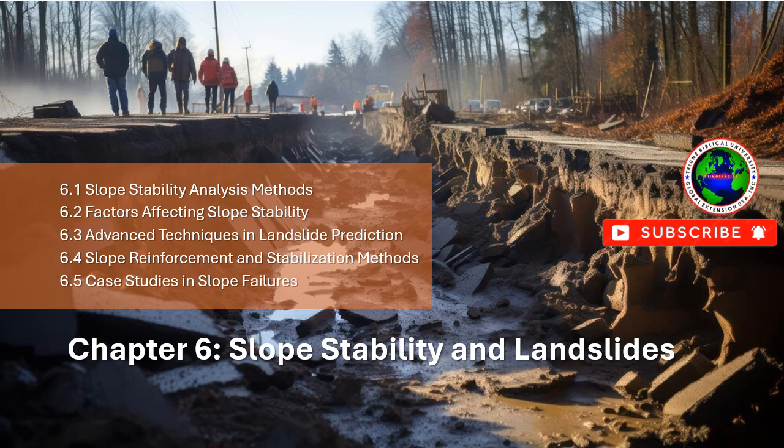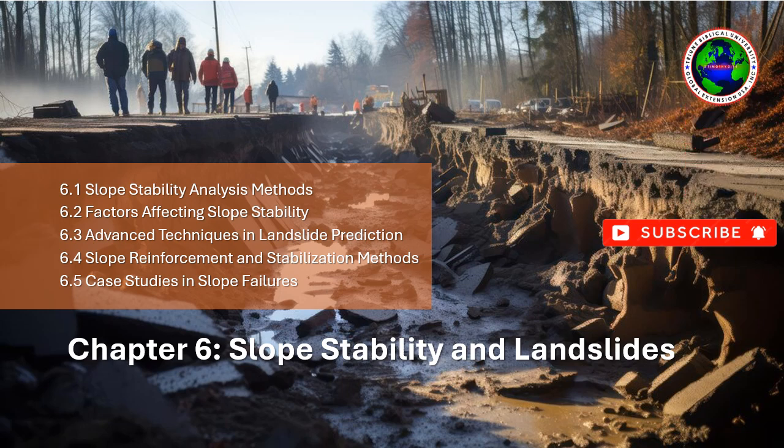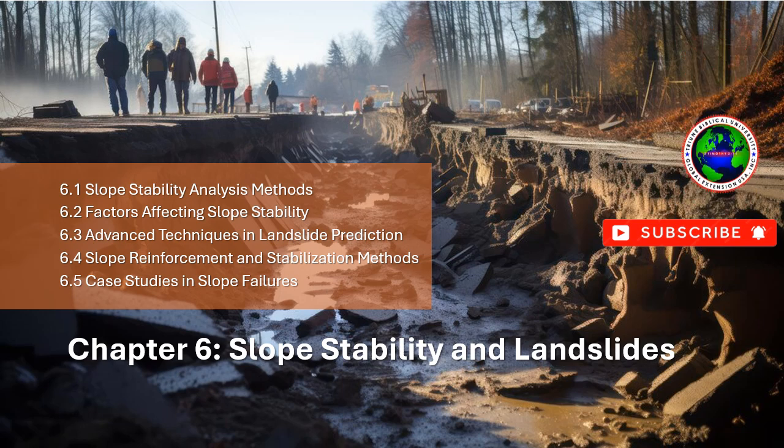Inadequate risk assessment. While the dam itself was considered structurally sound, insufficient attention was paid to the surrounding slope stability, leading to a critical oversight in the risk assessment process. Mitigation measures. Post-disaster reassessments.